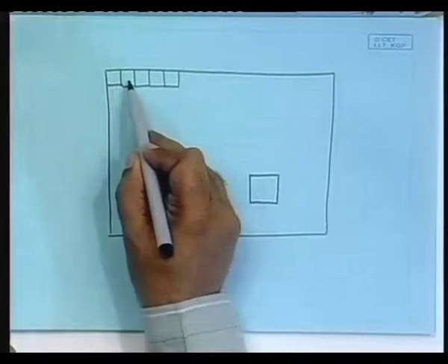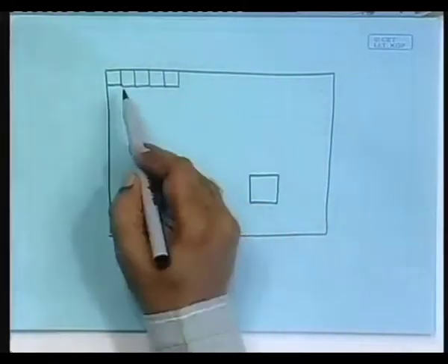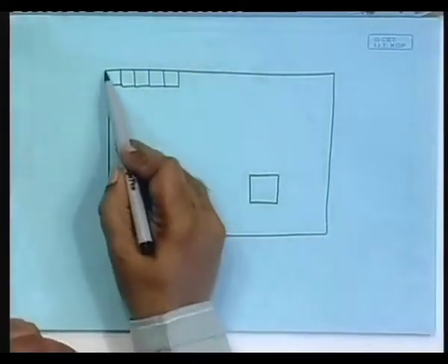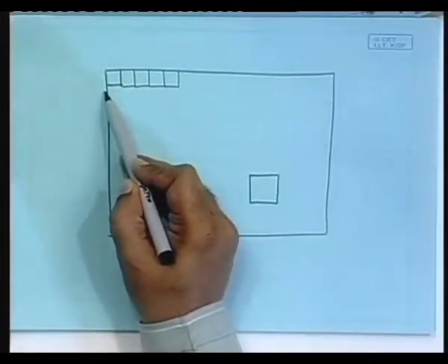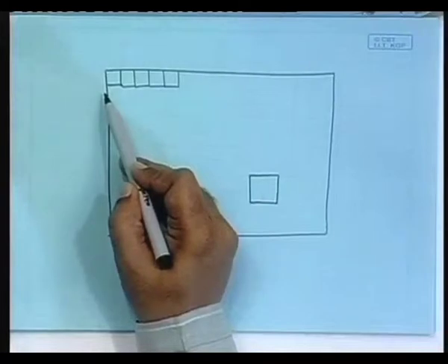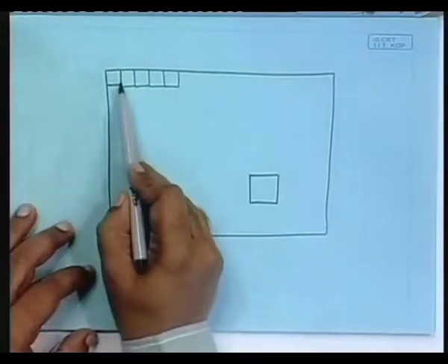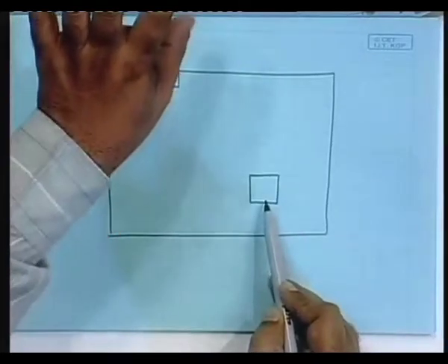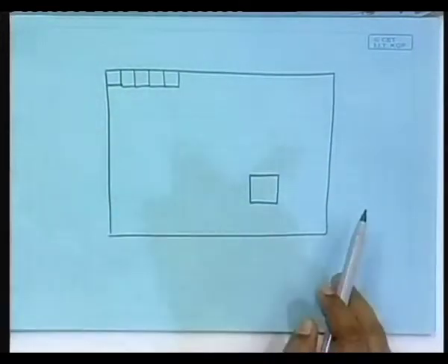Again we come here, search the whole image to find out which part it comes from. Normally these routines are written with a particular block size, say 8 pixel by 8 pixel blocks, or 16 pixel by 16 pixel blocks. And then if it is an 8 by 8 pixel block, you are looking for the 16 by 16 pixel blocks in the whole image, from where it gives the best possible fit.